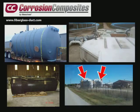Down below, we have two 40-foot diameter fiberglass domes on some wastewater tanks. They're unusual because they have a carbon veil that helps ground to prevent any static buildup. And it's extremely corrosive. Those are ribbed sections, and I think there are 10 segments to each dome. They were assembled on the ground and lifted in one piece.